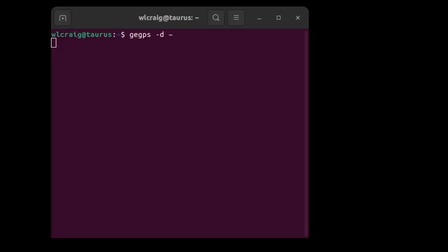Before we launch Google Earth, I just want to summarize what we've done here. The AVS-4000 SDR is providing GPS data that is sent to a pseudo terminal in the /dev/pts directory. GPSD reads that data from the pseudo terminal and makes that data available on a TCP port. We've now launched another client called GeGPS to extract just the geographical data and format that data so that it can be read into Google Earth.